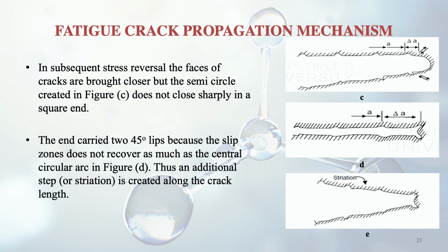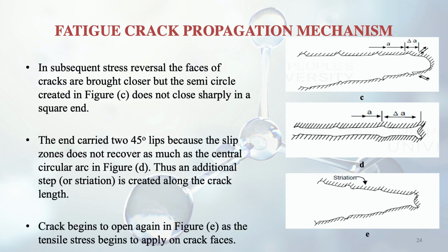Thus an additional step is created along the crack length. So you can see in the figure D, there is an additional step that is given by delta A, which has come in the figure. And this crack begins to open again in figure E, as the tensile stress begins to apply on crack faces again. So if we are applying it again, then the crack again begins to become larger, the tip tends to become larger.